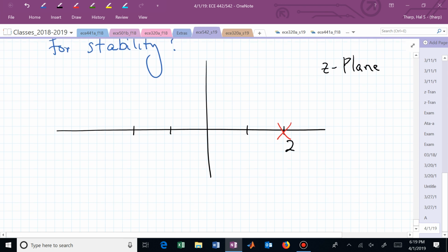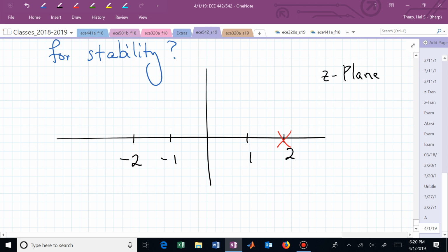And what value of gain do we need to have our system stabilized, or where are we on the complex z-plane, to first stabilize our system by adjusting this knob that is adjusting k? We will need to crank up the gain to get us to that triangle.